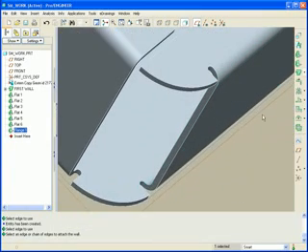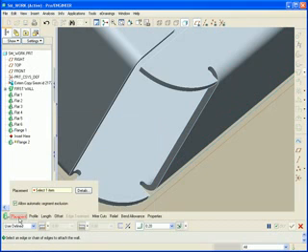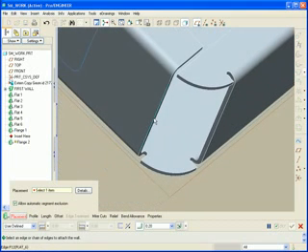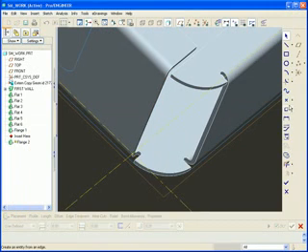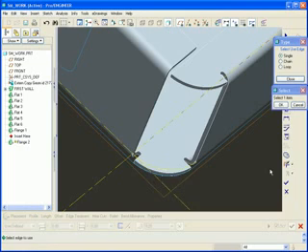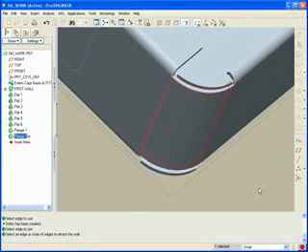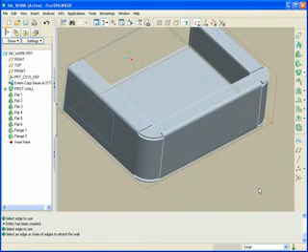Let's do that one more time. Flange, User Define, Profile, placement first. Pick the edge. Go to the profile, pick the sketch, and then use edge of the curve. Not the edge, the curve. Middle mouse, and there's that second flange.